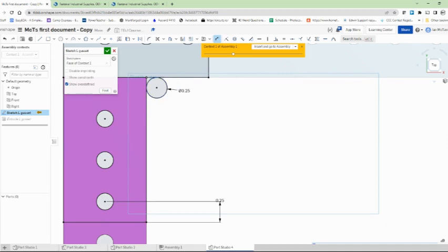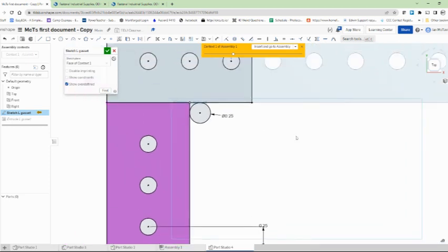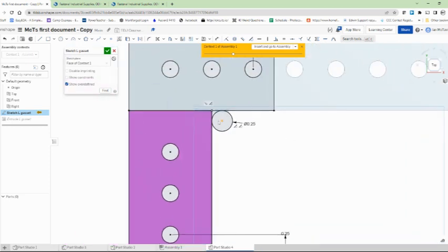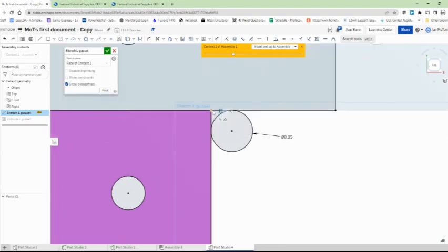So when I'm cutting an L gusset, our CNC router has a router bit that's a round circular bit that it spins and it carves material. And you can see this is the problem, is that when I get to the corner here, it will go there and go there. So it's going to leave a chunk of material in the corner. And we don't want that.